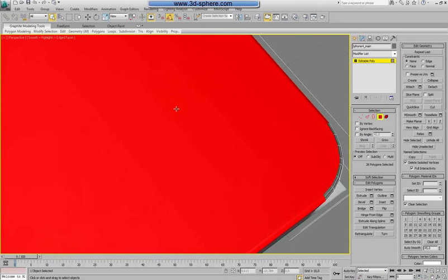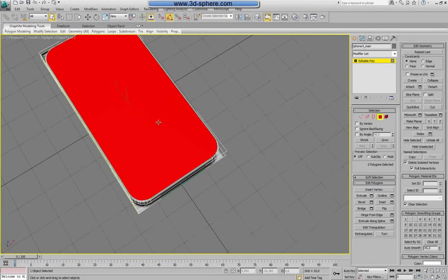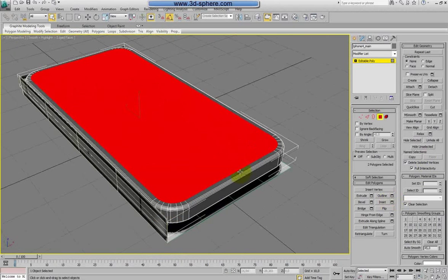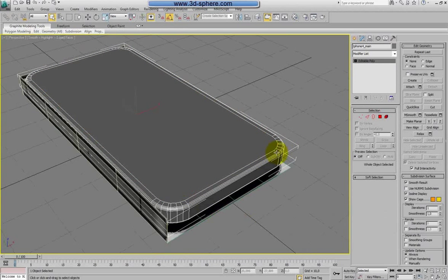Go back to poly, select the top and the bottom again and inset it. Yeah, this is okay. So I'm setting this, and I'm actually doing something like a border for the smoothing, because if I will not set it, the smooth will go from here to the center.